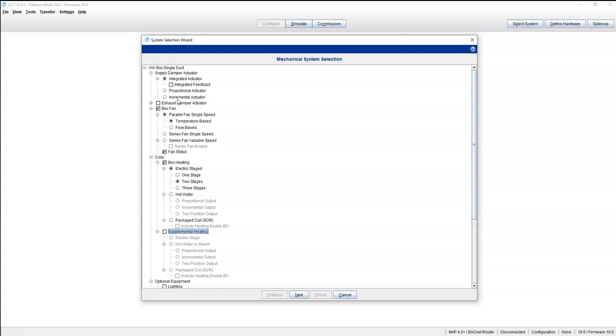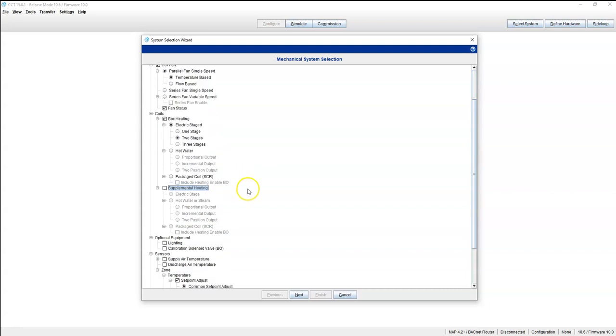The actuator cannot shut down to do its auto calibration. These controllers have to auto calibrate every 14 days. That means the damper is going to close off all the way, and then it's going to look at airflow, and it should say 0, and it's going to zero out the airflow, and then open the damper back up. That's how it auto calibrates every 14 days.